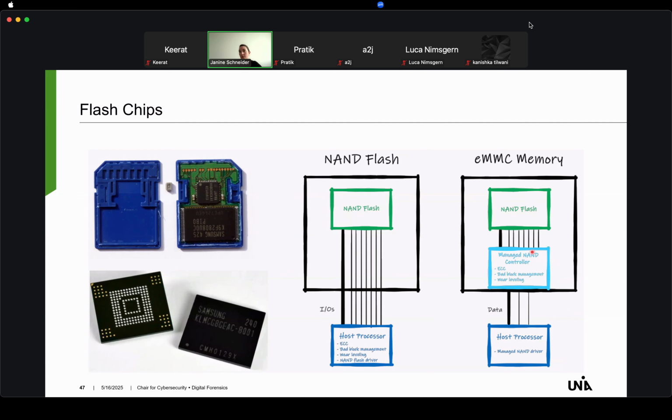They are usually 48 bits in length, including a memory address. There are commands for reading, writing, erasing, and they are specified by standards, for example the JEDEC standard. It must not necessarily be the JEDEC standard, but it is one of the most important ones. The standard specifies the commands that can be issued to this integrated controller to get the data on the NAND flash.